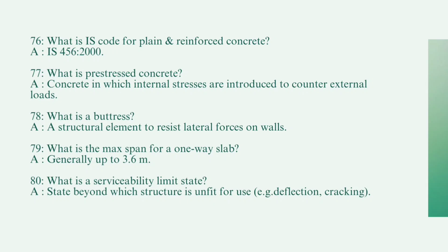The next is, what is a maximum span for the one-way slab? And answer is, generally it is provided up to 3.6 meter. Now the next is, what is a serviceability limit state? It is state beyond which structure is unfit for use, that is deflection, cracking, etc.